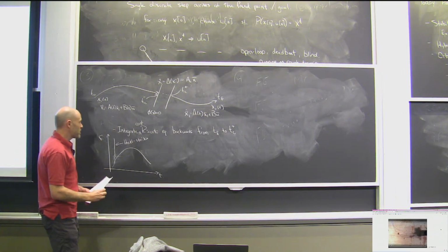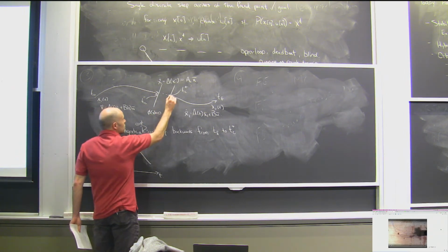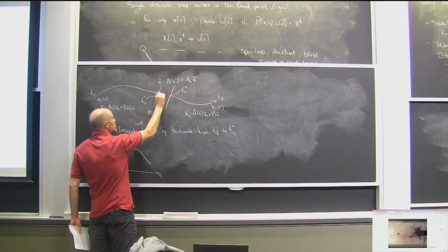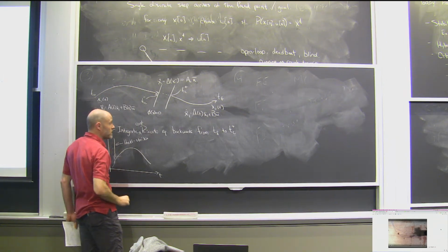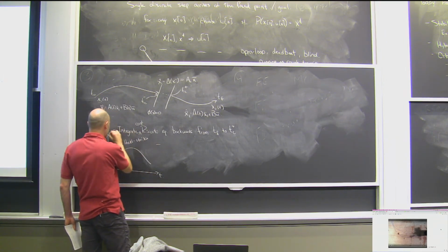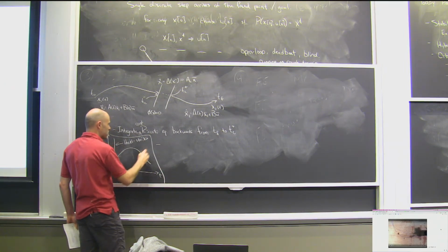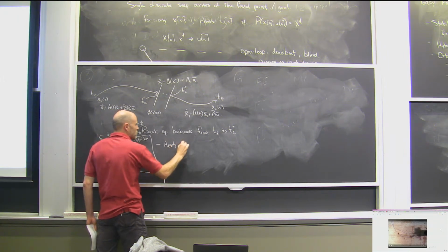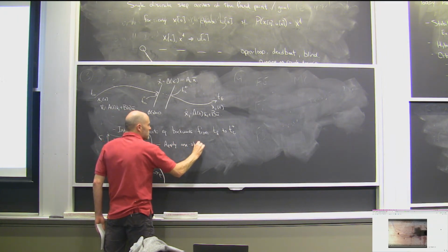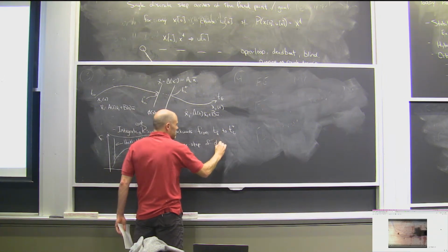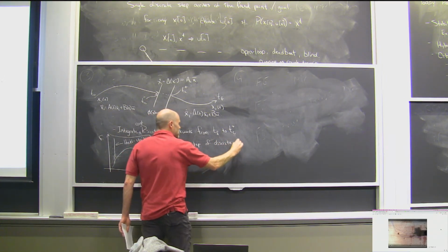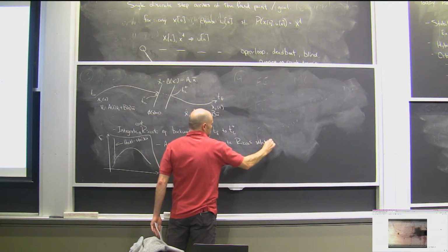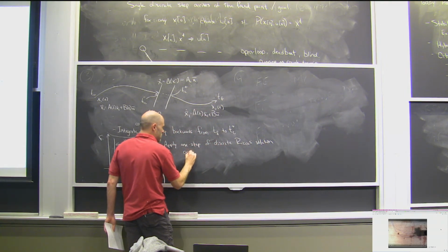Great question, okay. It turns out that the thing you need to do to continue to back up your cost to go across this jump and get back to the other continuous part we know and love is that step 2, which is right after heel strike, sorry, is to apply one step of the discrete Riccati solution across the reset event.